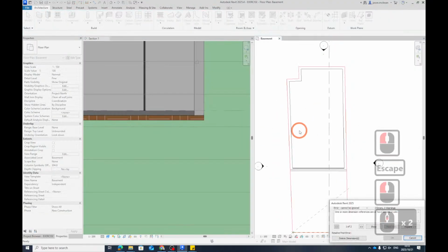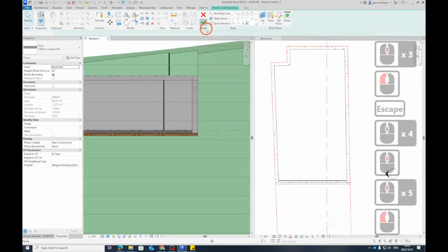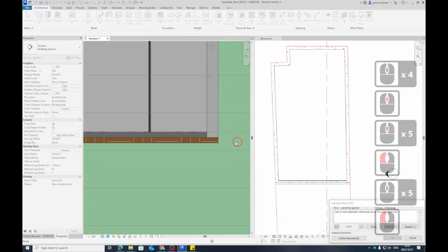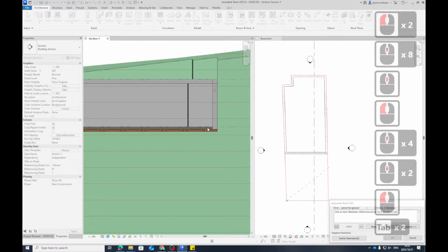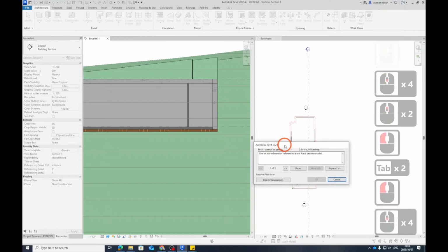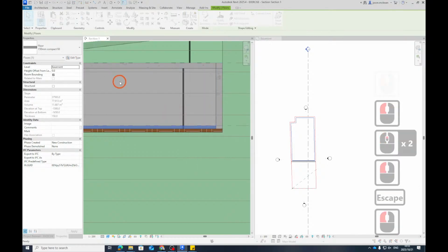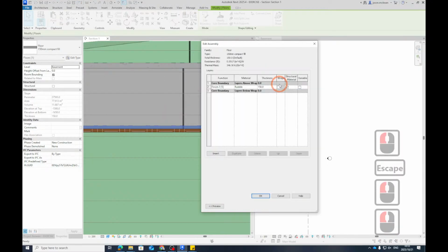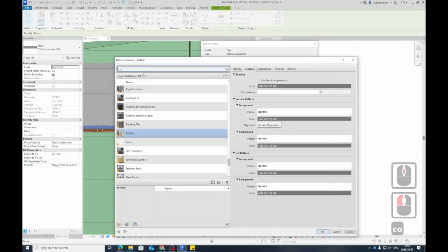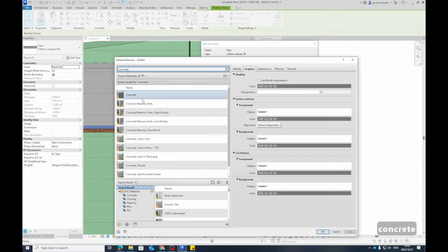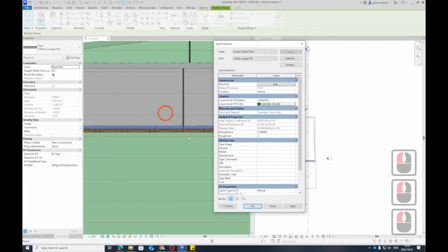that's what we do. Now there is a slight issue here that your floor material doesn't match your wall material. Okay, so if you want to join this information together, it's not going to join correctly. So we need to fix that. So if you press tab once or twice on your floor, delete dimensions, yeah. Okay, so edit boundary, edit type. Just make sure that if you want objects to connect, they must share the same material, and this will be concrete in situ. It will be this one, yeah. Press OK. Press OK. Apply.